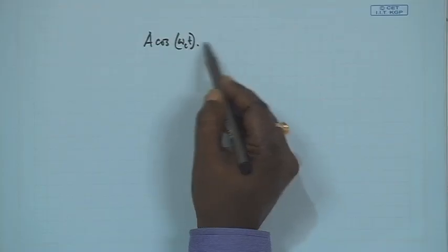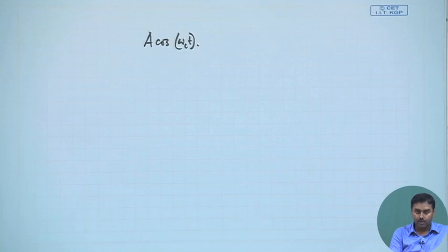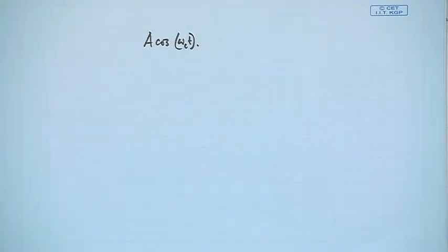So, an unmodulated carrier A cos omega c t is being transmitted. Of course, if it is FM modulated, there should be some phase term: for FM it will be the integral of m alpha d alpha times kf, or for PM it will be just m t times kp. We are just neglecting that phase term, that means unmodulated, just the carrier we are sending. For our purpose of analysis, you will see that it is not that much required, because at demodulation we will still employ FM demodulation, and we will get some insight.